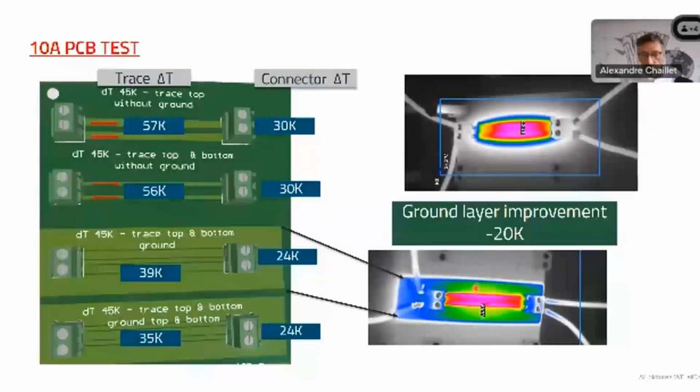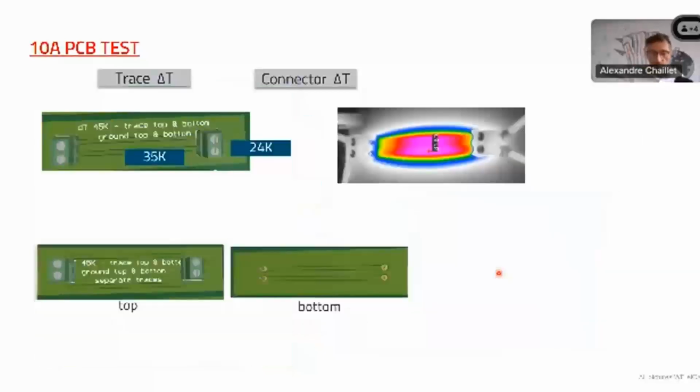And what you see here is that this dissipates a lot of the temperature, but when you reach the FR4, the FR4 is cold. And what does it mean? It means that you have no temperature dissipation anymore. So that really confirms that copper has a very good thermal conductivity, but FR4 does not.